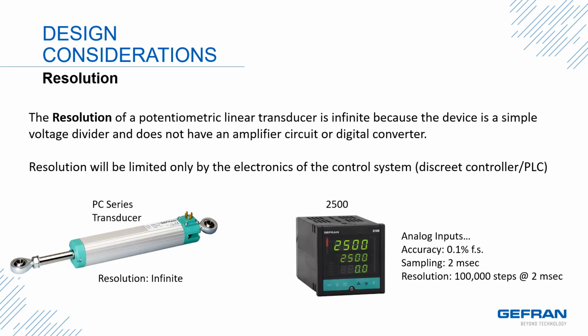The next design consideration is resolution. The resolution of a potentiometric linear transducer is infinite because the device is a simple voltage divider and does not have an amplifier circuit or a digital converter. Resolution of a system will be limited only by the electronics of the control system, whether a discrete controller or a PLC. In these pictures, you'll see a picture of our PC series transducer. The resolution on this transducer is infinite.